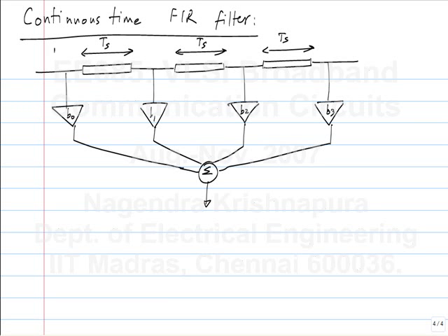Whatever signal appears here at point A appears at B after an interval of Ts. But in reality, the transmission line will have a loss. And also, what is the length required? Let's say we are talking about the assignment problem, 1 gigasample per second. What is Ts? 1 nanosecond. What is the length of the transmission line you need to implement this?